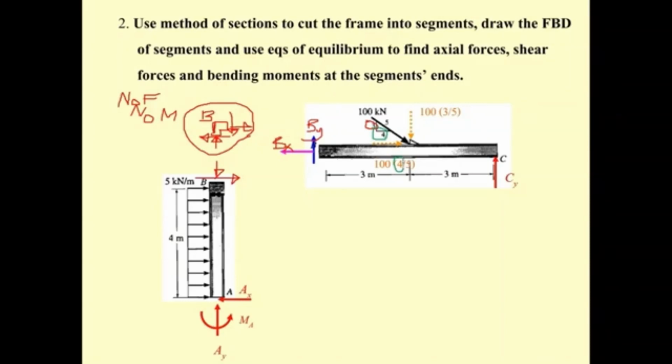If you project vertical, you use the vertical divided by 5. If you project horizontal, you use the horizontal length divided by 5. And now, if you like, you may determine the forces. By determining the forces, we start by taking the moment about B, summation of moment about B equal to 0.